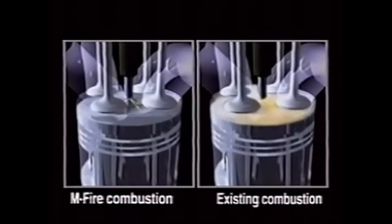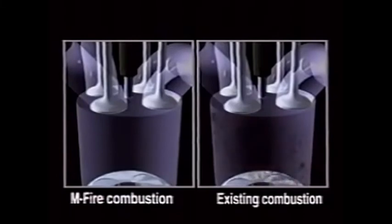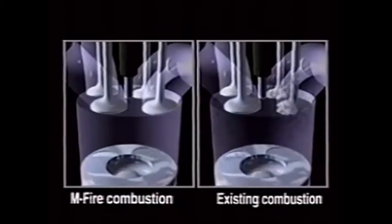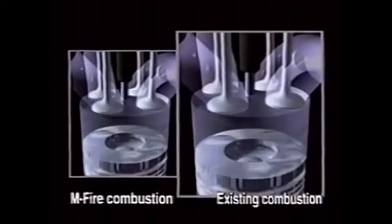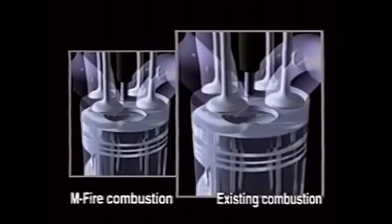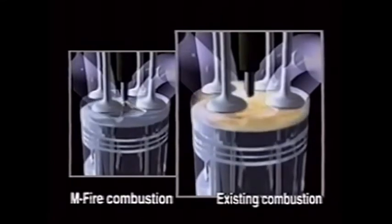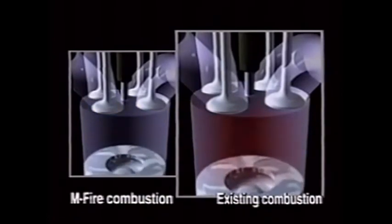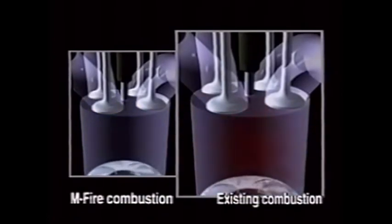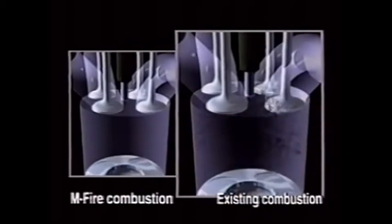Let's take another look at the differences between conventional combustion and MFire combustion. In the conventional combustion process, combustion begins when the piston is at the highest point in the cylinder. The resulting high pressure and high temperature combustion produces noise and NOx. In addition, the remaining fuel is not fully burned in the latter half of the combustion process, resulting in the formation of soot.